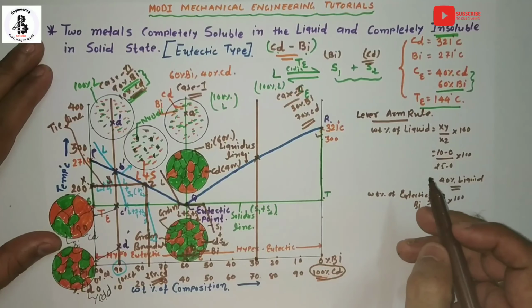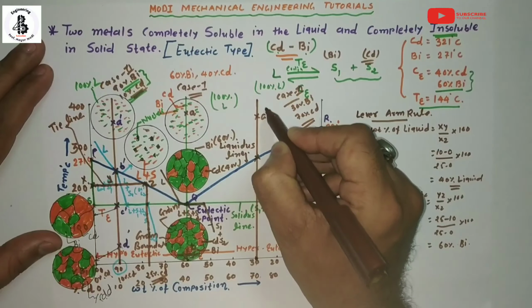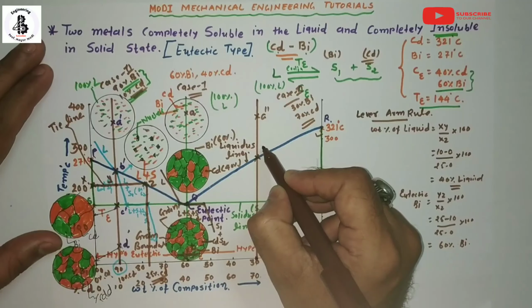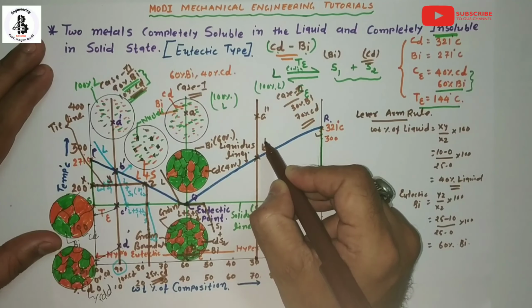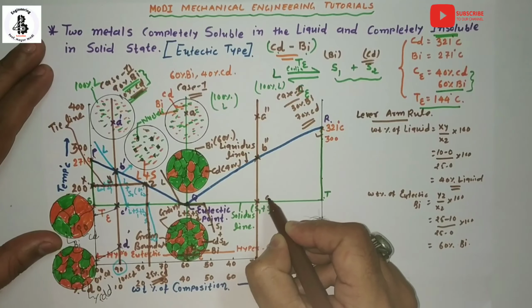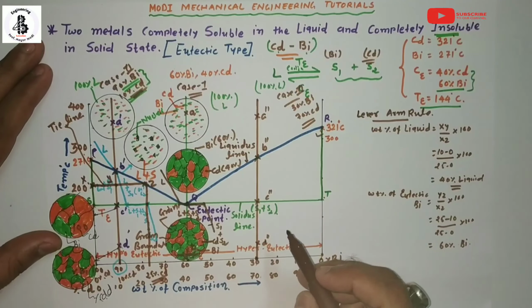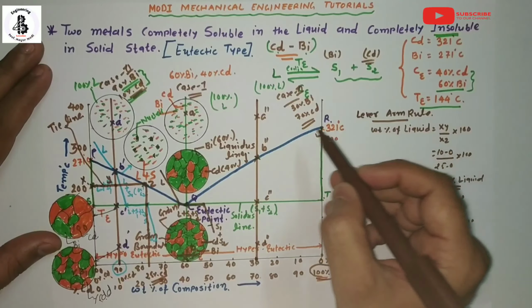Similar to what we already discussed with the hypoeutectic transformation, here the intersection with the Liquidus will be B double dash. Similarly at the eutectic transformation, C double dash, and at room temperature, D double dash. Now I would like to make a microstructure for the different points.